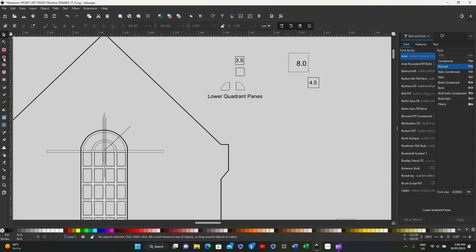So we first of all go to select, draw circle, as we've done before, press on circle, draw a circle any size you like, press on select, and change the width and the height to 7 millimeters. Once you have that, double click inside the circle and you'll find the handles that we had before. Click on this circle handle and just turn the quadrant around until it perfectly aligns. Press select and we now have the quadrant.